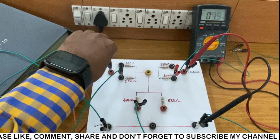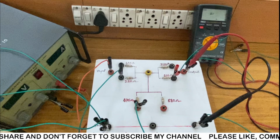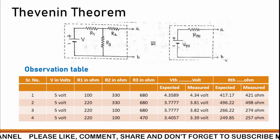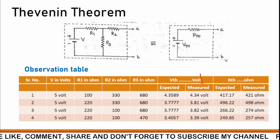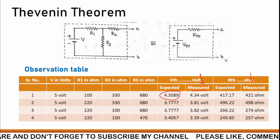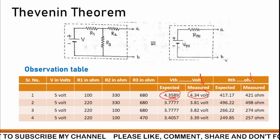And for the resistance RTH to be measured, I have to short R1 and R3. Then when I shift the selector switch to resistance, we are getting 0.257 kilo, 257 ohm. So you can see here I have written the measured voltage as well as the measured RTH. You can see from this the expected and the observed values are approximately equal. This is due to the fact that these are the theoretical readings and these are the practical readings.